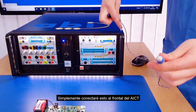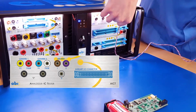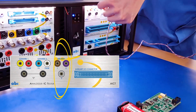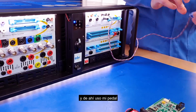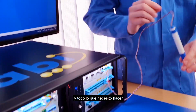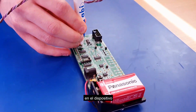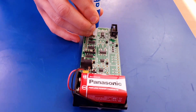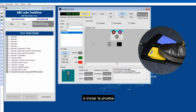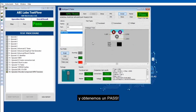I'll simply plug this into the face of the AICT, grey to grey, purple to purple, brown to brown. And then from there, using my foot switch, I can start the test. And all I need to do is place the pen probe on the device and start the test. And we get a pass.